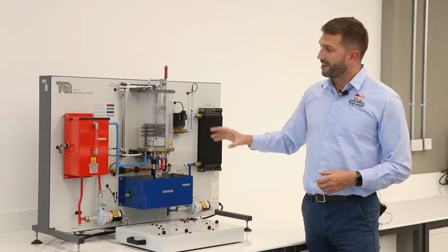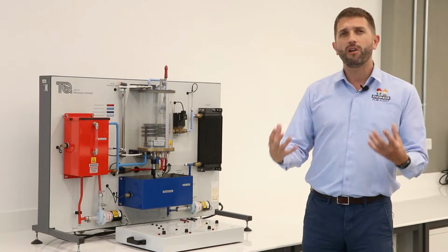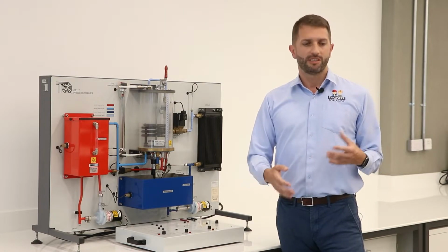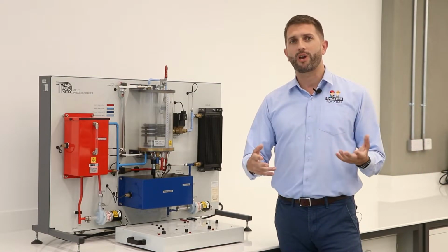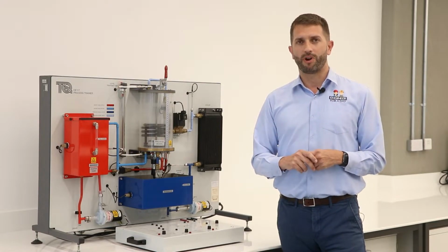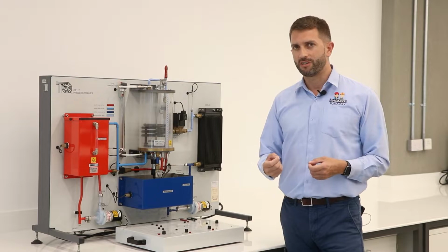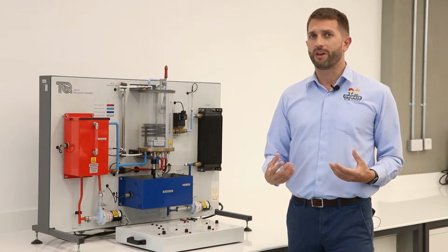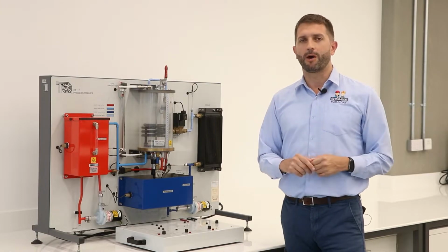The whole process trainer then has a number of sensors, whether they're measuring its temperature, the flow rate, the pressure, the level in the tank. All of these can feed back into the system to automate a process. Again, helping to take a raw material or a series of raw materials, combine them, perhaps in different ways, at different temperatures, at different pressures, to create that eventual high-value product that process engineers design. So the role then of the chemical engineer and the process engineer is to design that process, to optimize that process, to do it in a very economical way so that you're adding value each way, and of course, then getting that ultimate economic return from it.